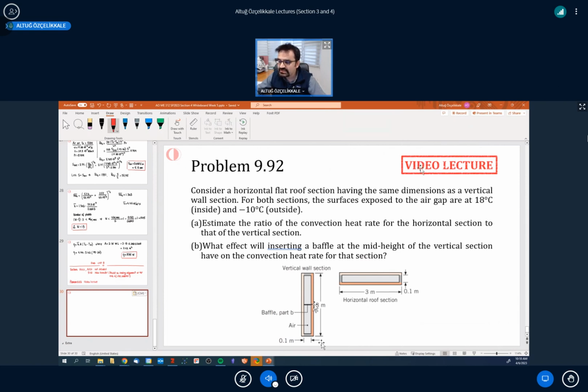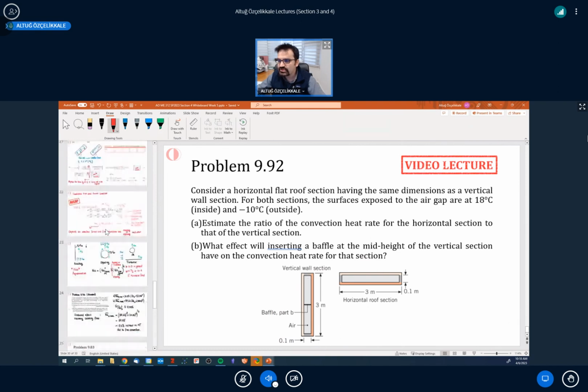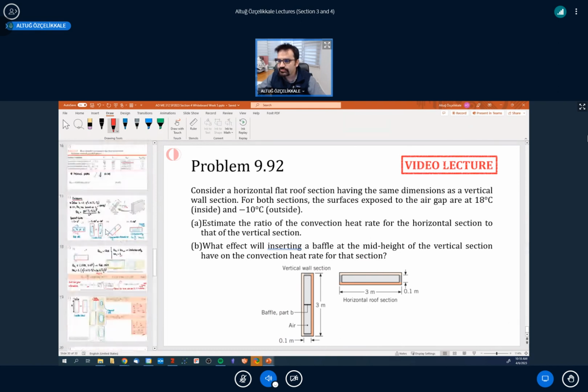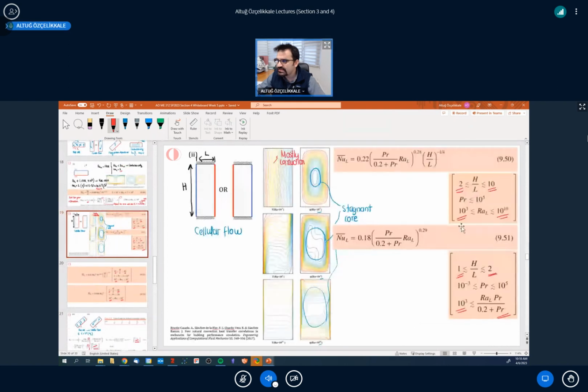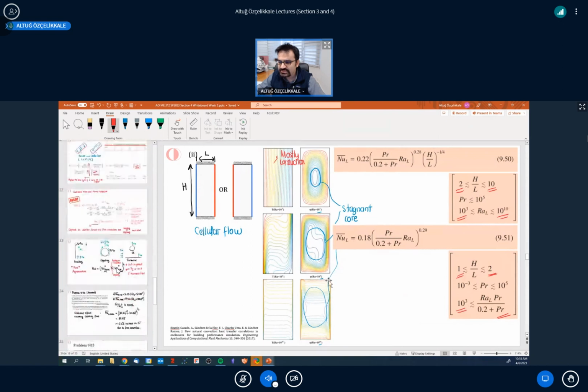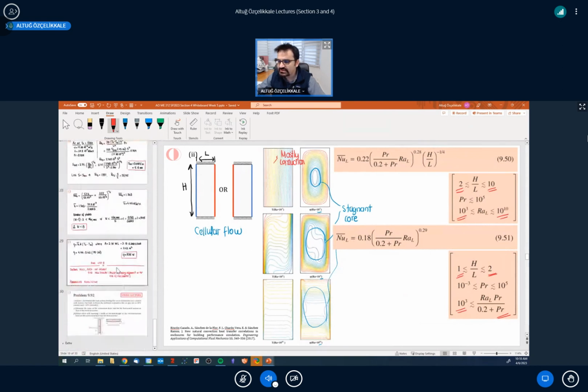potentially to introduce some additional structural integrity, we are adding some elements like baffles right over here. That's actually creating additional, separate spaces, like two different cavities, that has the effect of changing the H over L ratio that we have covered in a vertical cavity. Remember that it's quite important what kind of H over L ratio you have. So this baffle has the effect, for our calculations, of changing this H over L ratio.